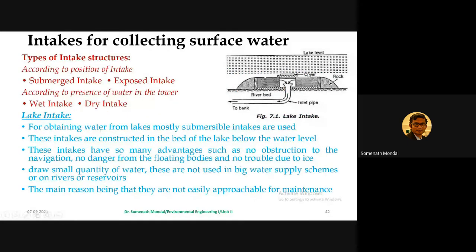This portion is slotted. If you see, just let me show you. This is the area which is slotted. So we have the cover and we have some slits in it through which water can come. However, all those debris or ice crystals would not be able to pass through into the withdrawal conduits.